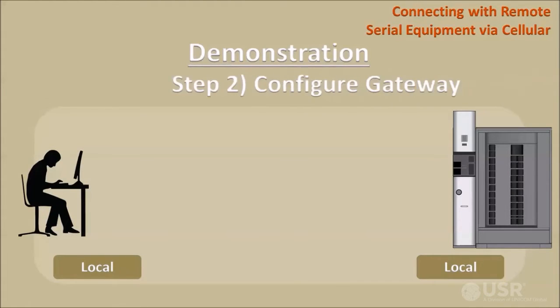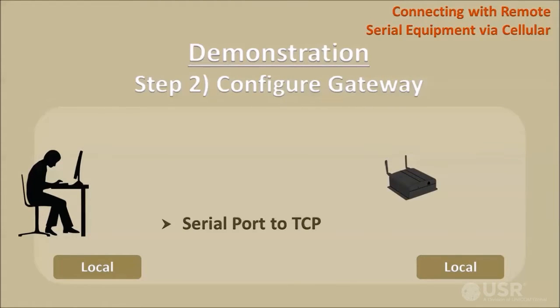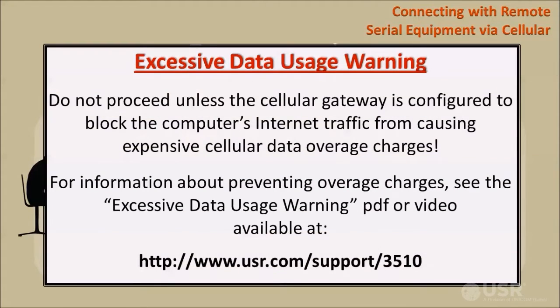Now I'll configure the cellular gateway for a serial port to TCP and ICMP. Before proceeding, be sure that the cellular gateway has been configured to prevent unintended excessive data usage. Details about excessive data usage can be found at this USR webpage.